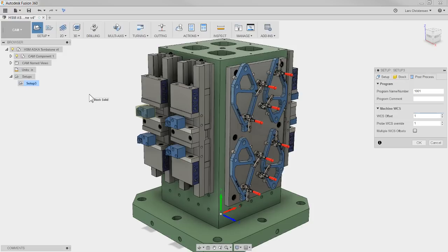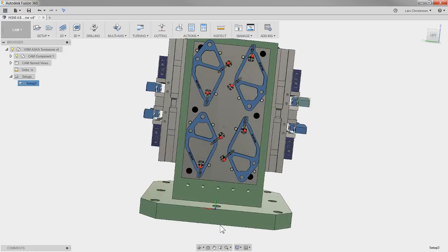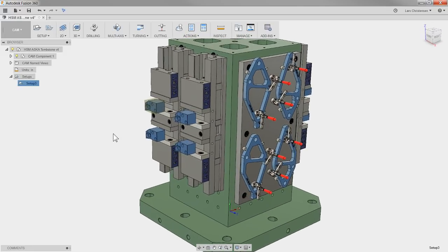We will deal with the other way with multiple work offsets in just a second. So with this way here, hit OK. This setup tells us that Z plus is pointing towards this face. So this is side 0. G54 is the center of rotation. So now I can start programming my part over here.